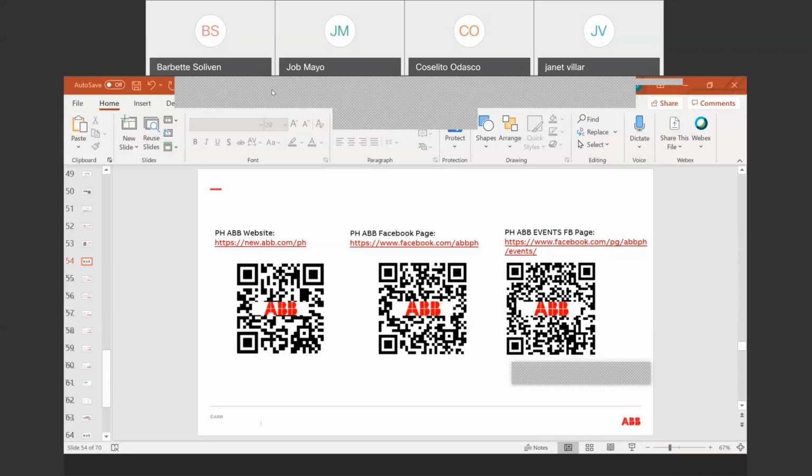Again, if we are using IEC 60898-1 and it will be installed in residential dwelling units, the K factor is 1 for 6 kA and below, 0.75 for a certain value, and 0.5 for 10 kiloamps and above. So it would vary depending on the standard and on the K factor of the circuit breaker. But yes, it is applicable. But I'm not sure why you need 100% ICS for residential facilities.